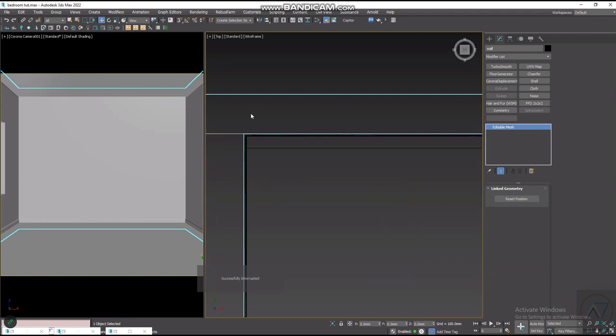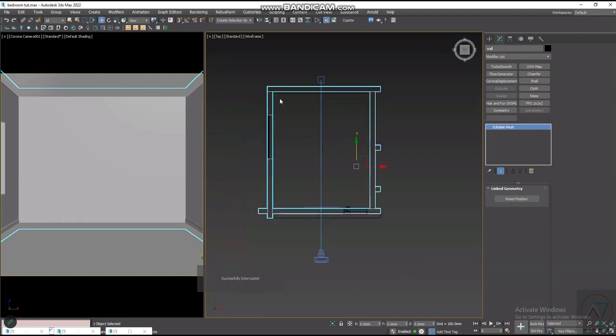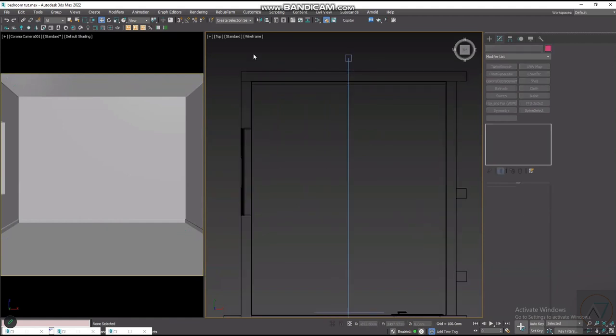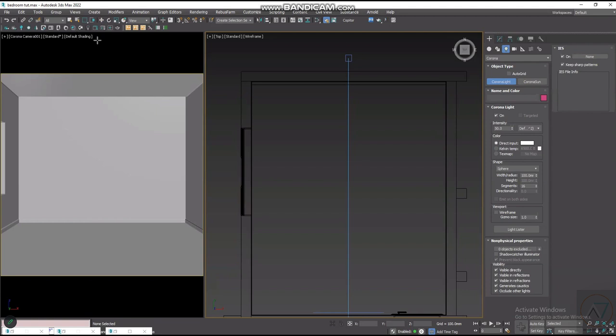Then let's just create our line lights and start importing, because there's not much time again. Sorry. So to create the artificial light, just come to this guy here. You can see create Corona lights, click on it. Your Corona toolbar might not be here, it might be at this left side. Doesn't really matter, I just enjoy putting mine there. So just come to Corona, look for Corona light in there. Then now we have a Corona light here.